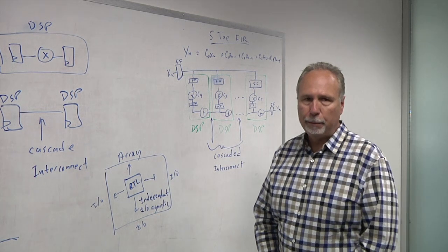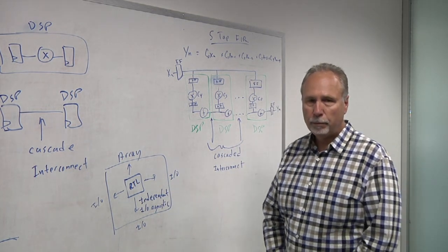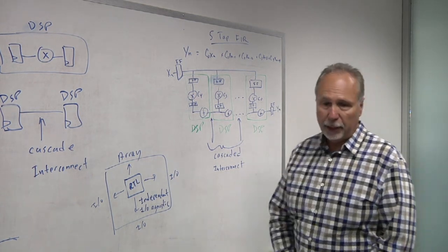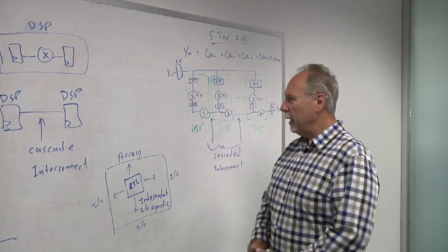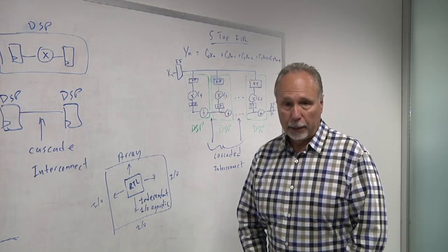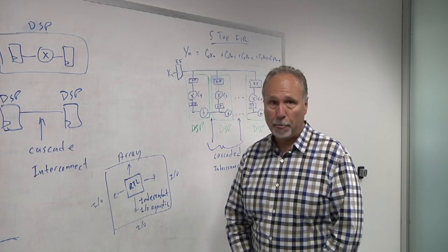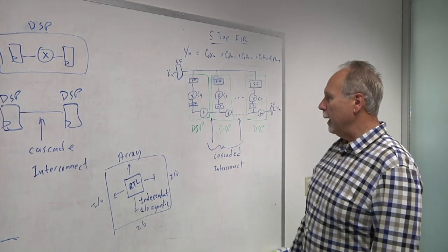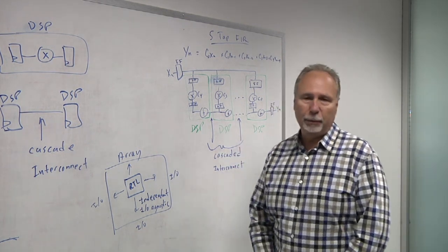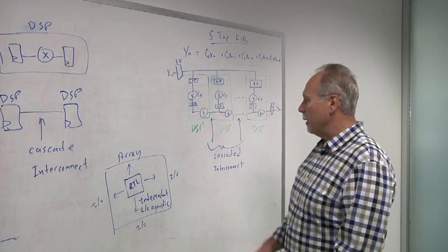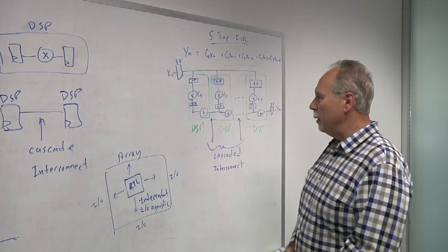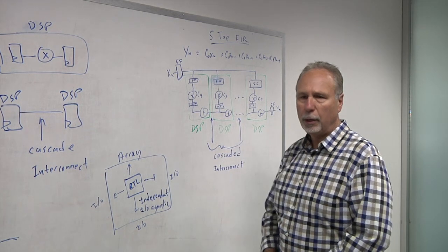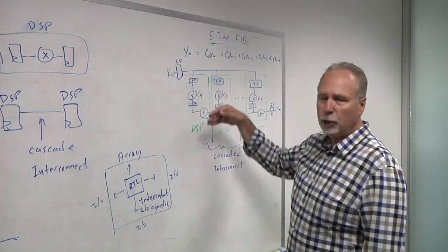They don't have to go through an interconnect fabric, and that could give you a much higher frequency in that example. So if you do all these things right, how much of a performance gain do you actually get? For a 5-tap FIR filter in a 16FFC design, for instance, you could get up to almost 400 megahertz in worst case timing and process. And if you don't take any of this into account, what would it run at? It could run a lot slower, maybe 200 megahertz, because the interconnect is a big contributor, and pipelining, if you actually have flip-flops inside your DSPs, also will impact how fast you can do the multiply.